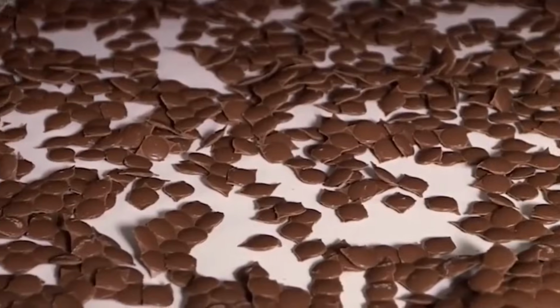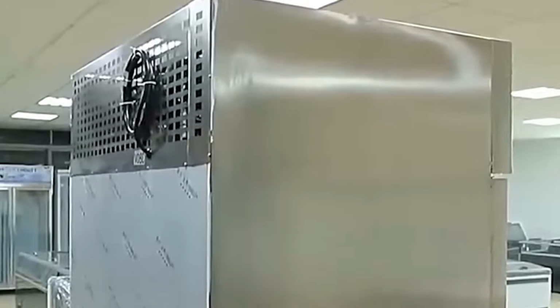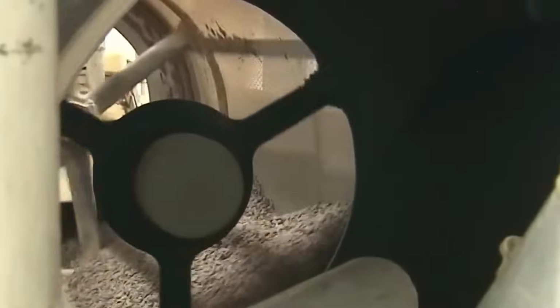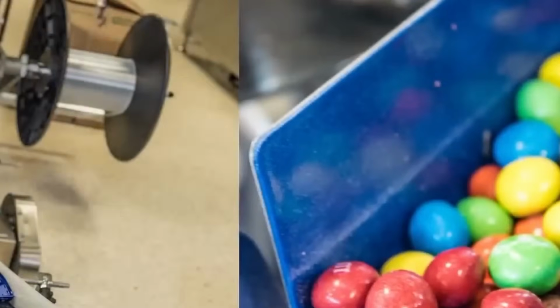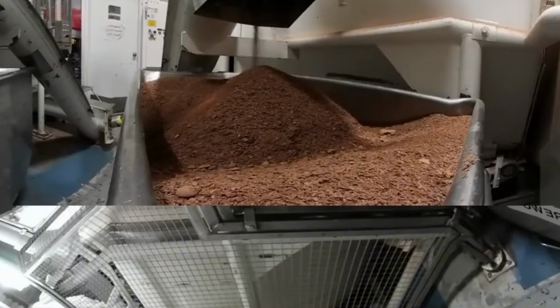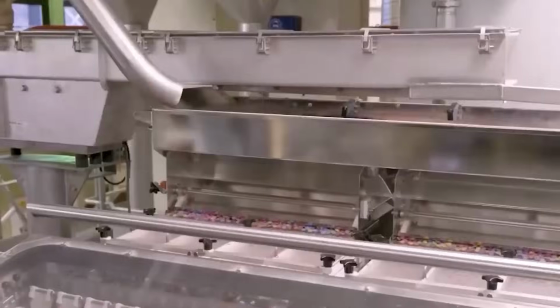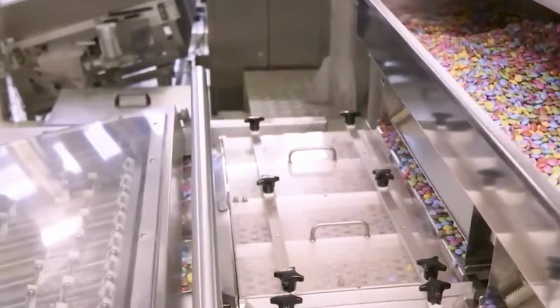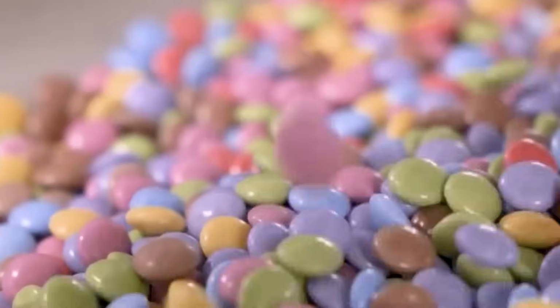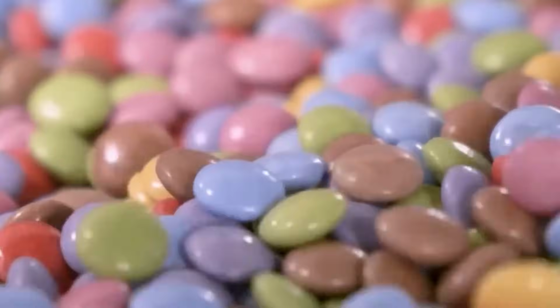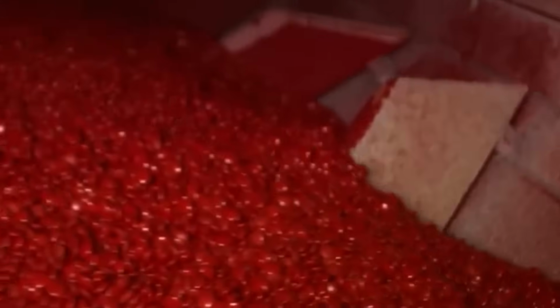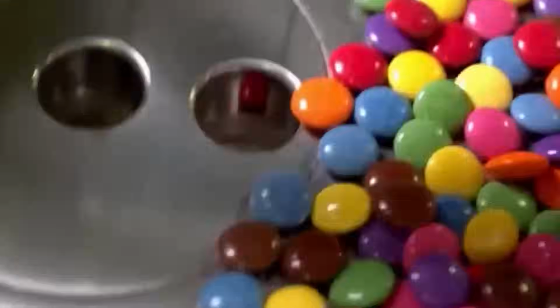Cooking is conducted at temperatures between 115 degrees Celsius and 120 degrees Celsius, and continuous agitation prevents scorching and ensures homogeneous heating. A vacuum step may be applied after atmospheric cooking to reduce moisture content without exceeding target temperatures, improving chew texture and shelf stability. Once the required consistency is reached, the caramel is transferred to a cooling table or cooling drum equipped with scraper arms, which reduce the mass temperature to below 50 degrees and prepare it for forming.